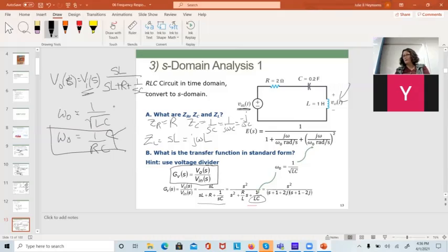Inside of most electronics, we're talking about it being dominated by R's and C's, because when the magical triangle was invented in the 60s, the op-amp, at that point, you did not need inductors to do analog circuits. You could get that extra pole in there with the op-amp. So we like our R's and C's. Inductors are big, bulky, and expensive.